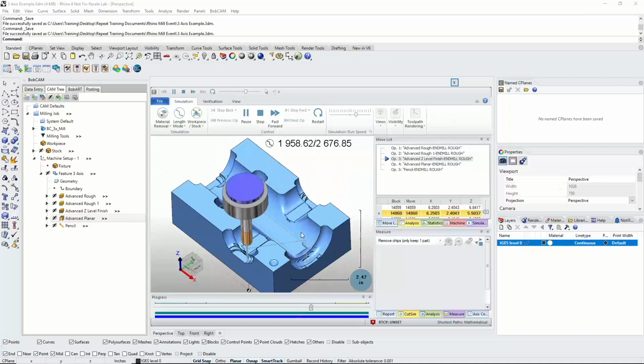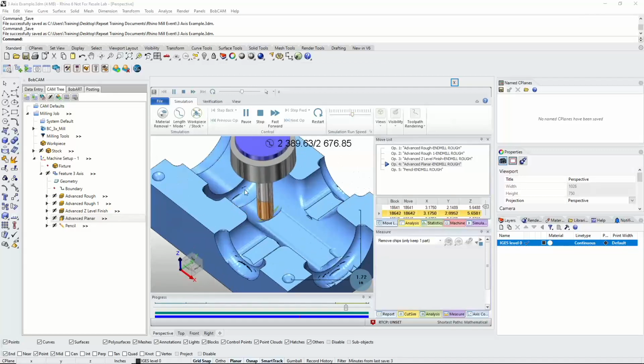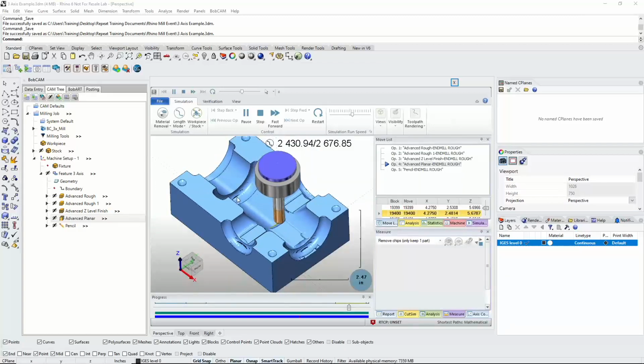And we'll see it's just going to run. So it could have been clipping something in here that the planer is going to clean up, and that's unexpected for a collision there. And that's why that thing might have happened. So we'll let that almost done. Now we're onto our planer. And so the planer is just going back and forth across there. Back and forth in there. And you'll see the excess material that we have down in there. And that'll hopefully be cleaned up unless we didn't set enough allowance.